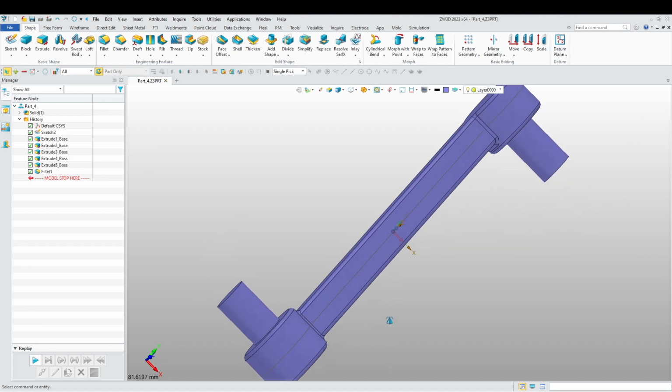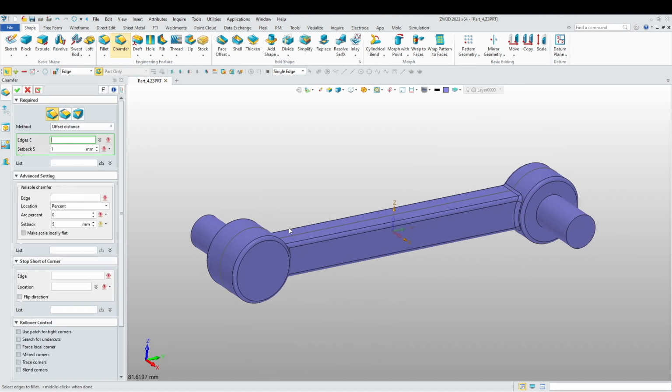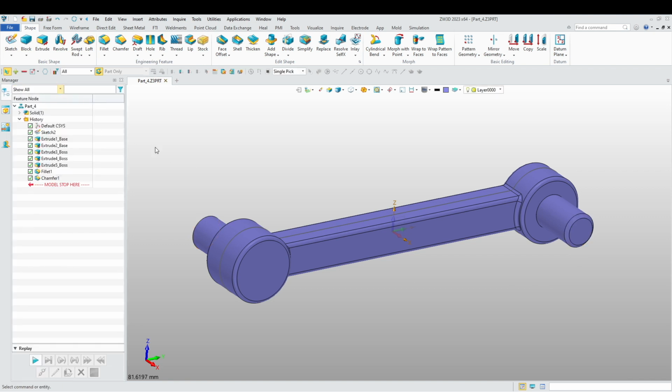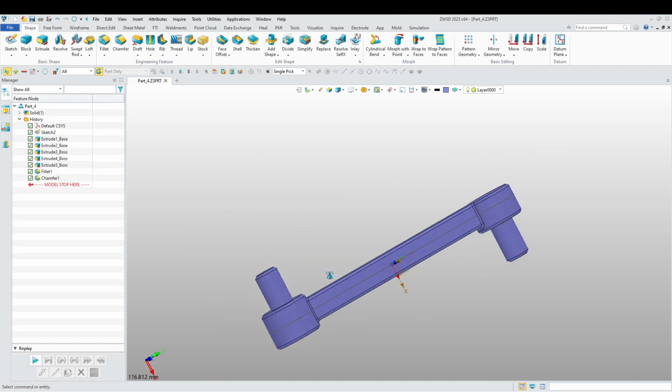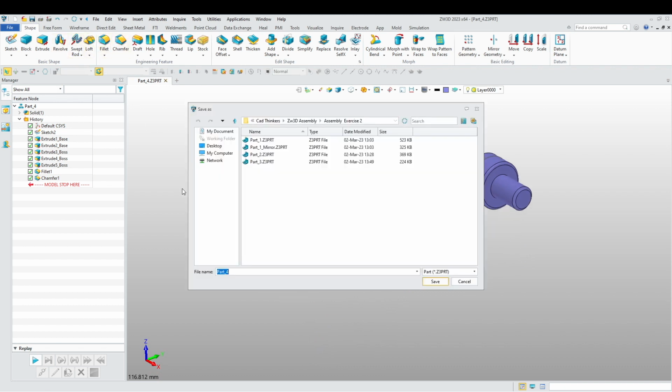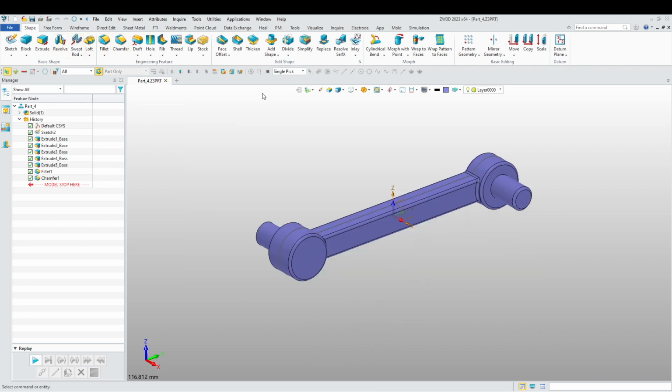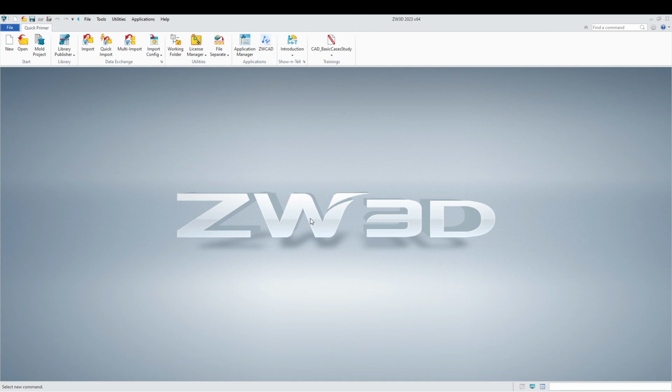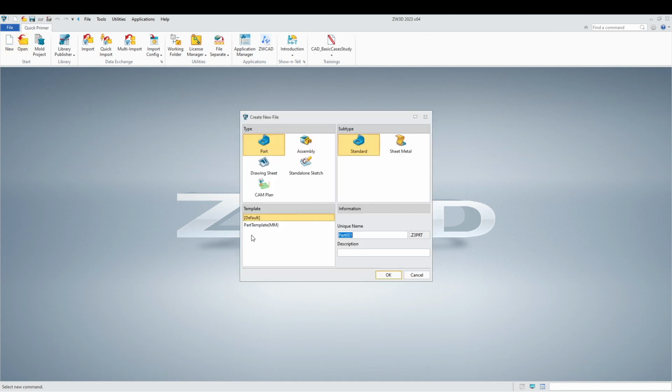Okay, good. And let's just add a 1 millimeter chamfer there as well. All right, there we go. We have part 4 done.